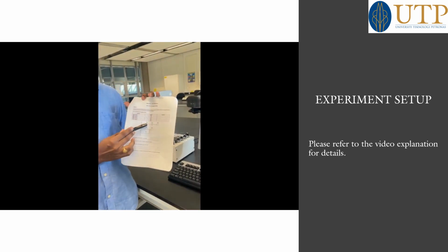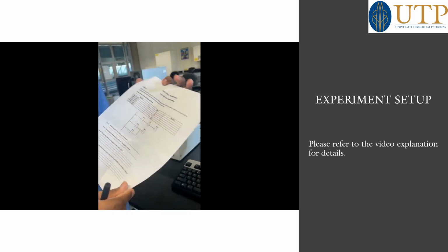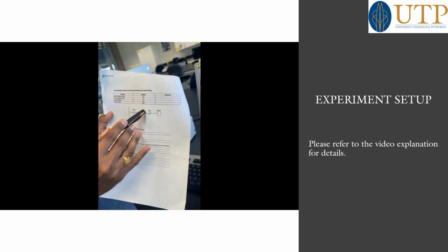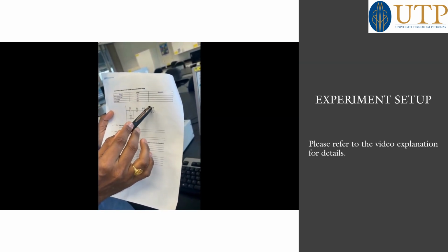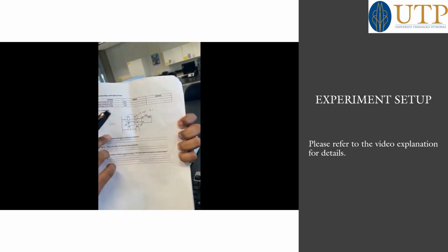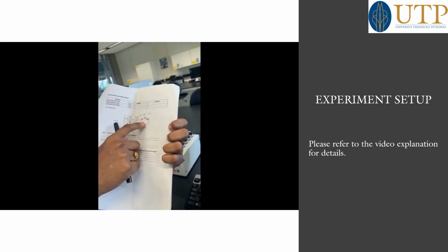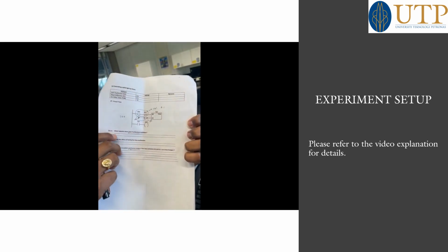The first one is normally open circuit. Okay, and the second one is normally closed circuit, which has a slash in the circuit, and this one is the output circuit, and this rectangle box is a timer on delay. So if you want to do anything automatically after 5 seconds or 10 seconds, you need to use this rectangle box, that is TON, timer on delay.